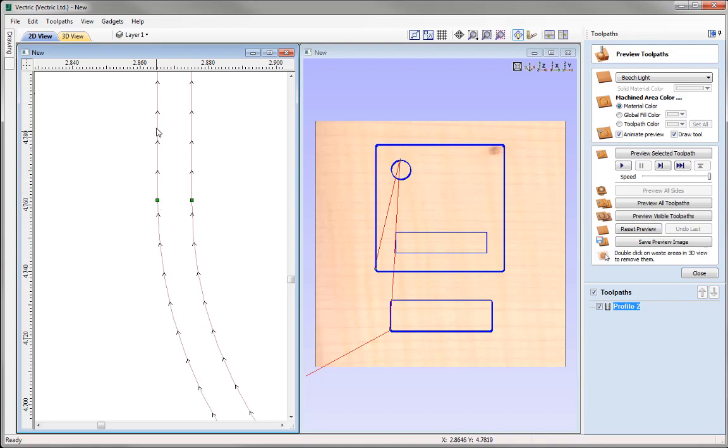Now this first path is going to come in and it's undercutting by the 0.01 allowance that we set, and it will just cut all but the last pass. And then it will move on to this pass here, and this is the final pass, being the only pass which actually cuts to size. And what it does, it uses more of the length of the cutting teeth to machine away the tiny amount of material that is left on for the last pass, where we reduce the amount of witness marks on our part.